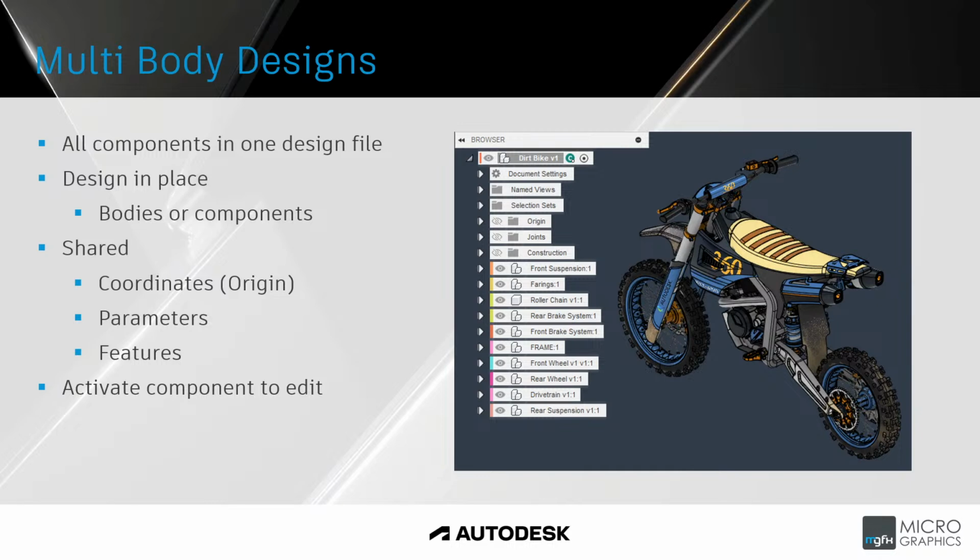In this case, if we want to edit specific components, you would typically activate the component. Let's see the roller chain there in the browser, roller chain V1. You could activate that component and you would then be editing within that component, and anything you do for that component will be captured in its history.